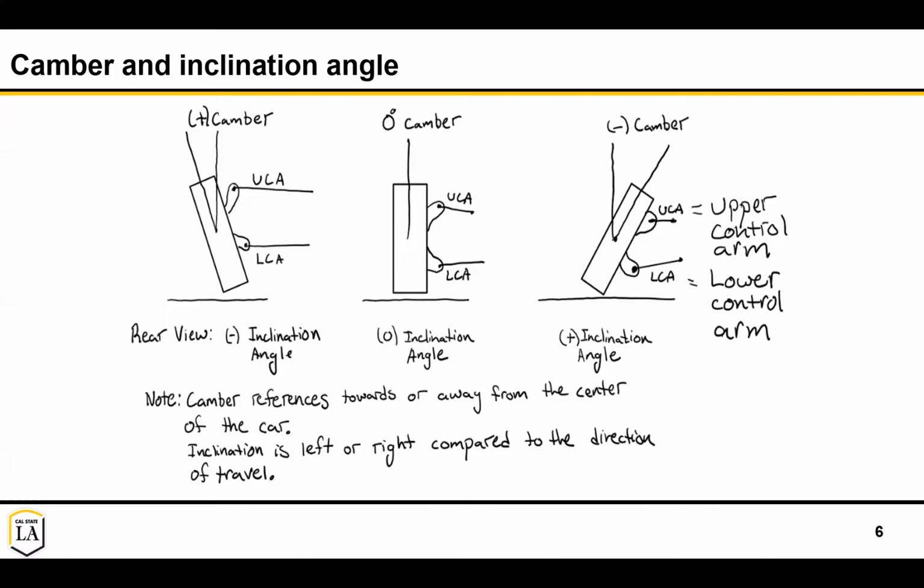So typically tires want to be close to vertical in order to maximize grip, or have a little bit of negative camber. And what you want to make sure to do is keep your tires from going into positive camber while you're going into turns, and keep in mind not only because of roll and the tires traveling in roll, but also just compliance in the system can cause your tires to go into positive camber, where you can lose quite a bit of grip.